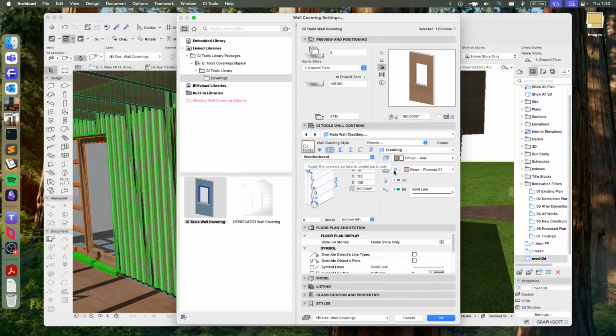So essentially what we're saying is that if you're using weatherboards, for instance, if we turn on this option, it will put plywood on the outside of the weatherboards, but on the inside, underneath, the part that's facing the wall that you don't see, that will retain the building material. And the reason it does this is so that, again, if you want to be able to produce an accurate schedule of the amount of surface area that you have, so if you are applying paint and you want to know how much area is painted, you can use this option here to make sure you only paint the outside of your claddings, and then you will get an accurate area value for your calculation based on the surface that you apply there. So we can do those things there.